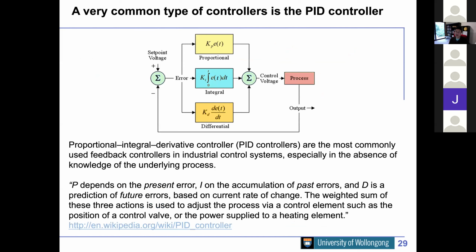So let's look at PID. We watch the video. Basically, it's three terms added together. Proportional. The input to the PID controller is the error signal, which is the difference between the reference and the output. So the error is your input. And the controller has three gains. The first gain is KP, the proportional gain. You can see it multiplies with the error signal, e(t). So we call it proportional. It's proportional to the error signal.